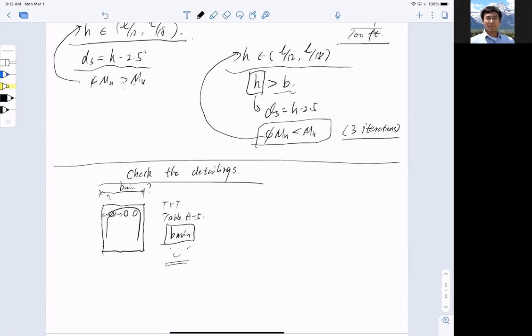But a significant number of us just didn't even bother, right? They got the moment right, and they're happy with it, and they just left it and just put the bars in an illustrative fashion. So let the construction people figure it out, and that's not right. Okay, so we really have to check on the bar detailing for both types of problems. If you didn't check the bar detailing, I normally deduct 5 points out of 35. Okay, so that is about the first exam.